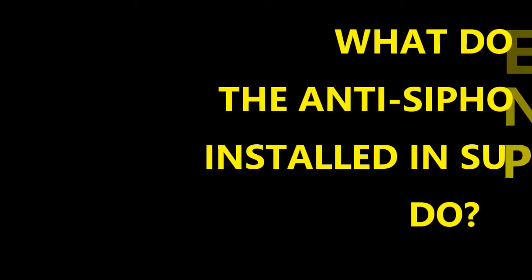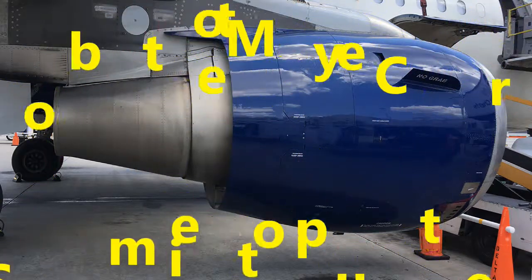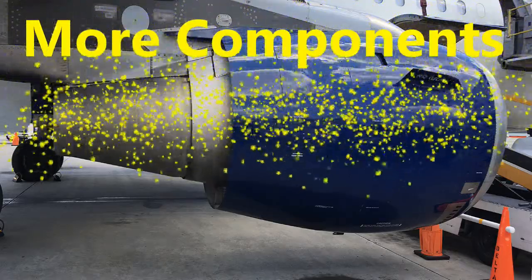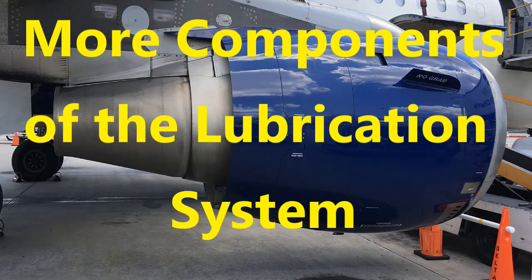so it doesn't drain the tank. Okay. Now the temperature sensor and pressure switch, you have a signal that's used by the ECAM system, and that's to obviously give the indication for the filter clog, and then also a temperature sensor. The temperature sensor is going to be on the filter housing of the lubrication unit. Okay, you have that lubrication unit I mentioned before. And by the way, what you're seeing here on the diagram, there's a supply area and a scavenge area. It's part of the lubrication unit.